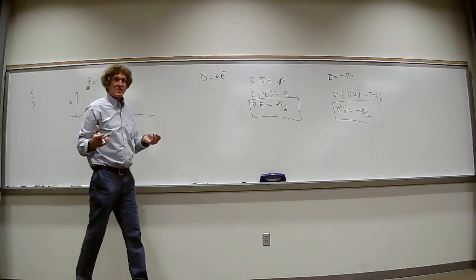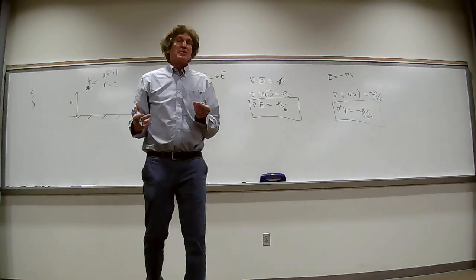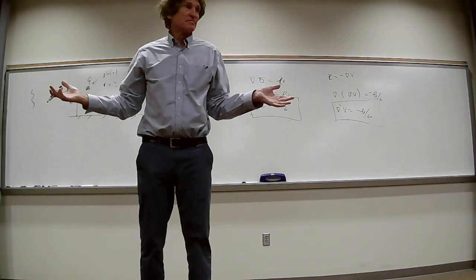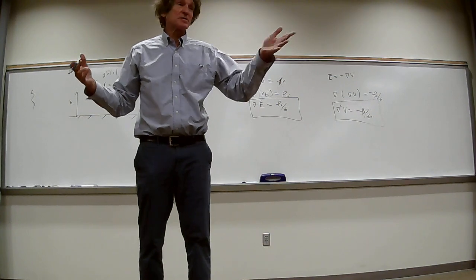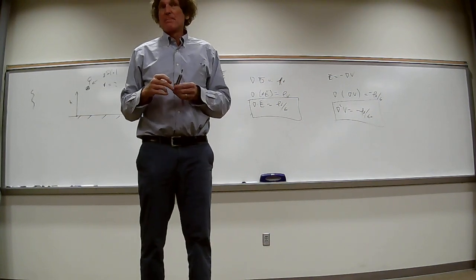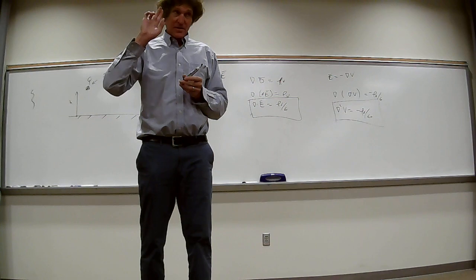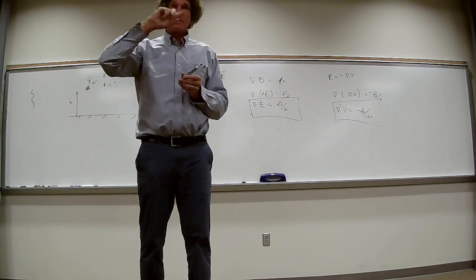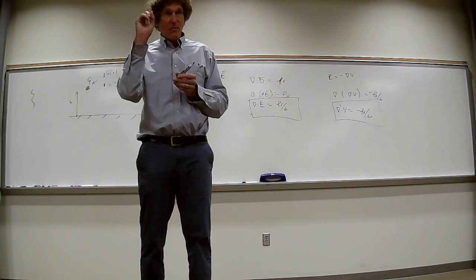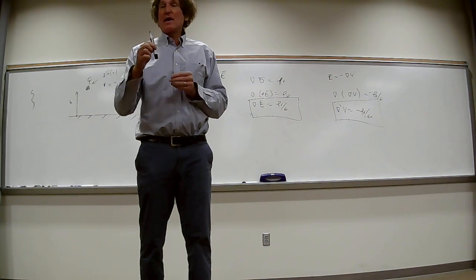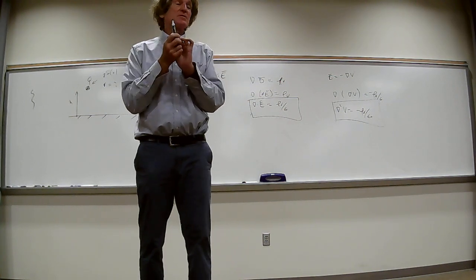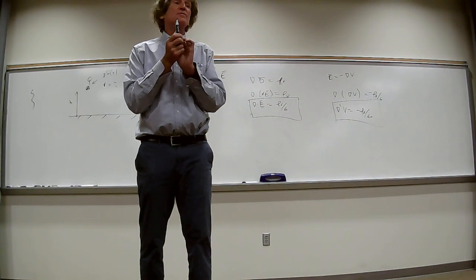You know what a delta function is? In your own words, what is it? Think of back in the day when you did circuits. What did a delta function tell you? Or system, linear systems. Well, if you integrated a delta function in the time domain, from minus infinity to infinity, dt, you got 1, right? It said the area under that curve was 1, but what about the height? At the point where the delta function goes from nothing to everything, it goes to infinity.